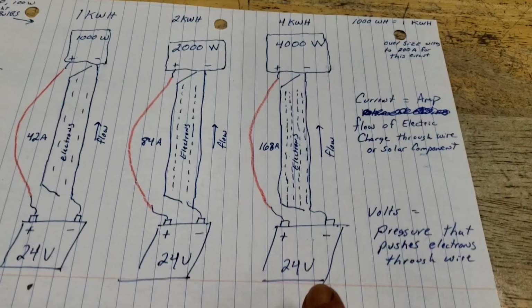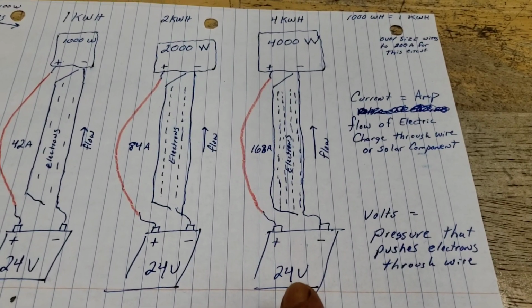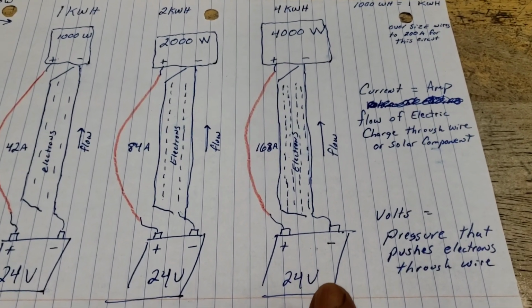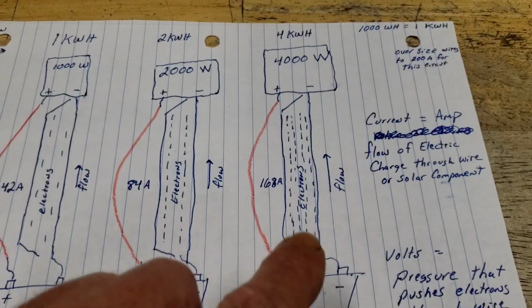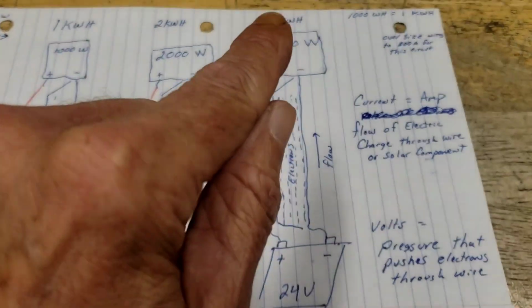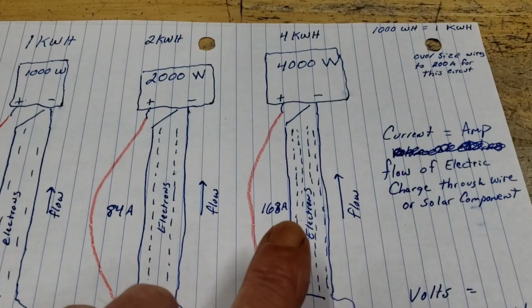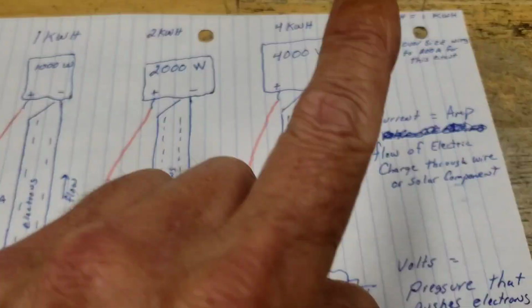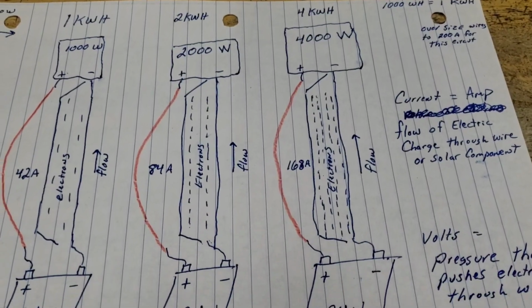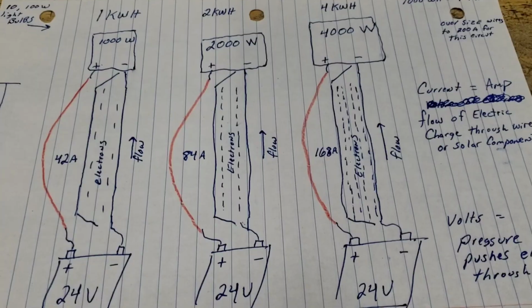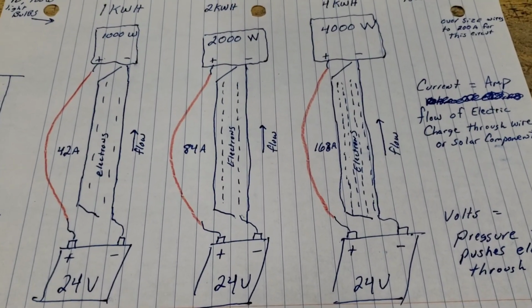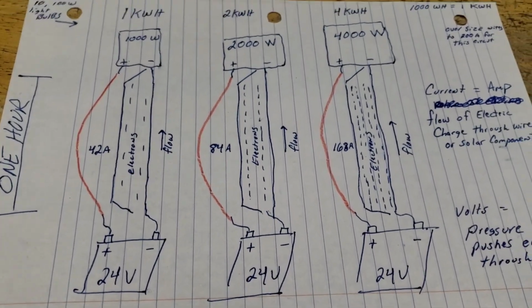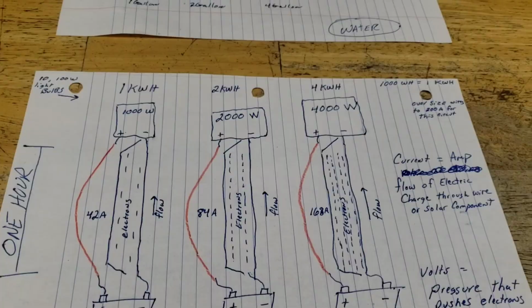To kind of just give you a quick Ohm's law look. Now, since this is 24 volts, if this was 240 volts, like for your house, like we just went over some of the big hot water heater and all that, because of Ohm's law, 240 volts, with this load on the end, all we would do is add a decimal point right in there, 16.8 amps. So that's where that Ohm's law comes into play, where I always say to everybody, the math doesn't add up, like often is my phrase, because my brain is really good at just seeing this and knowing if it's right or if somebody's explaining it to me. But I think I covered everything I wanted to cover.